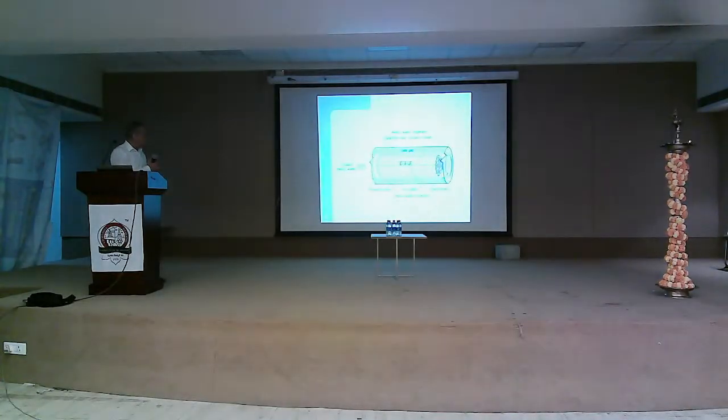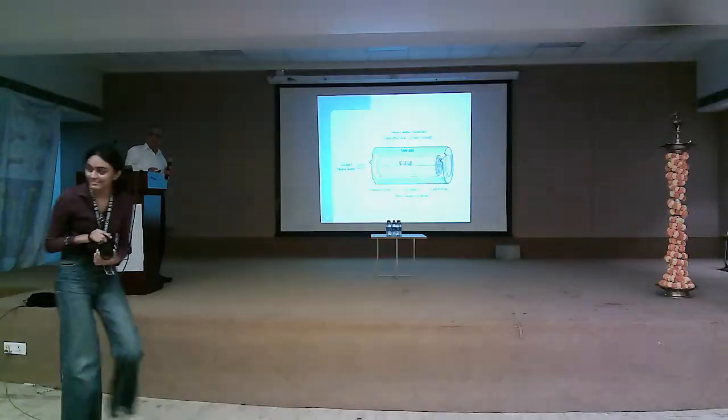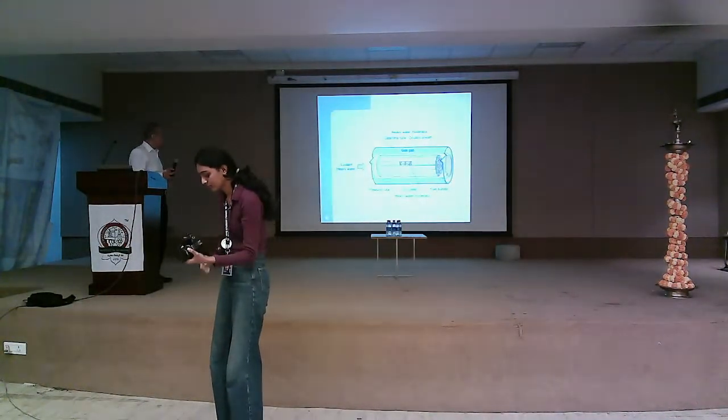This shows another picture, in which this is the uranium oxide. Uranium metal is not used because uranium metal, around 600 degrees, changes its phase, so its volume increases and breaks the cladding. So they use uranium oxide, which can go to high temperature.